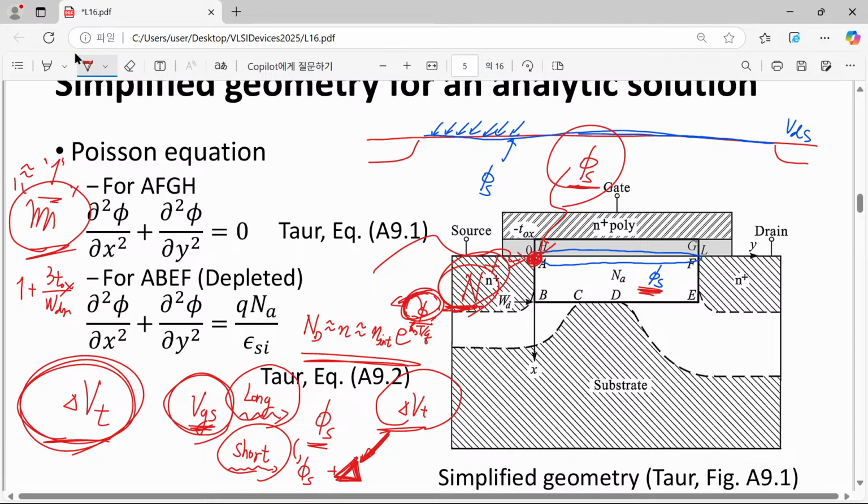The contradiction is our assumption of a MOS-like system that is obtained from just a one-dimensional vertical MOS structure. There is nothing outside there, and we just considered this x-directional system. The surface potential obtained that way is not very rigorous for our current calculation.